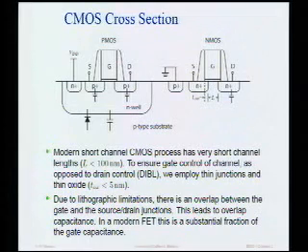So in this class, we're going to be dealing with short channel transistors, so we have to be aware of these issues. Now, the other non-ideality that's process-induced is this overlap region. Ideally, the gate should not overlap with the source and drain, right? The gate should control the channel. Because if the gate overlaps with the drain, we get a capacitor from gate to drain, right?